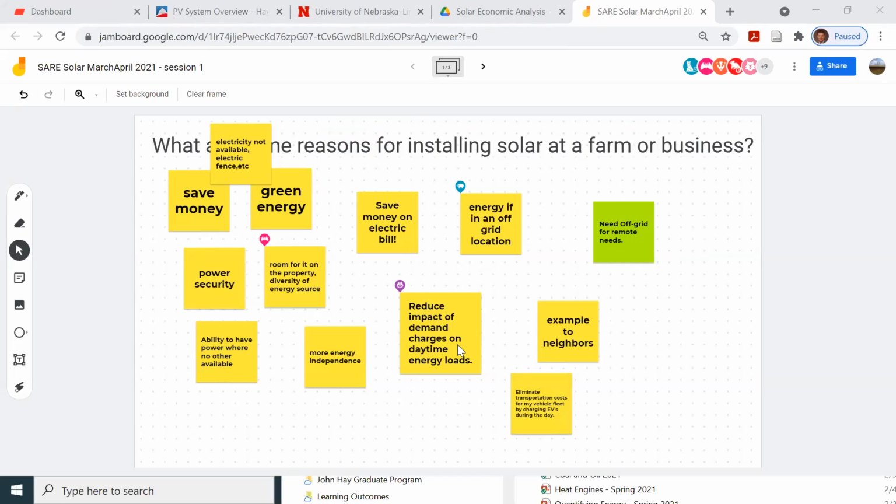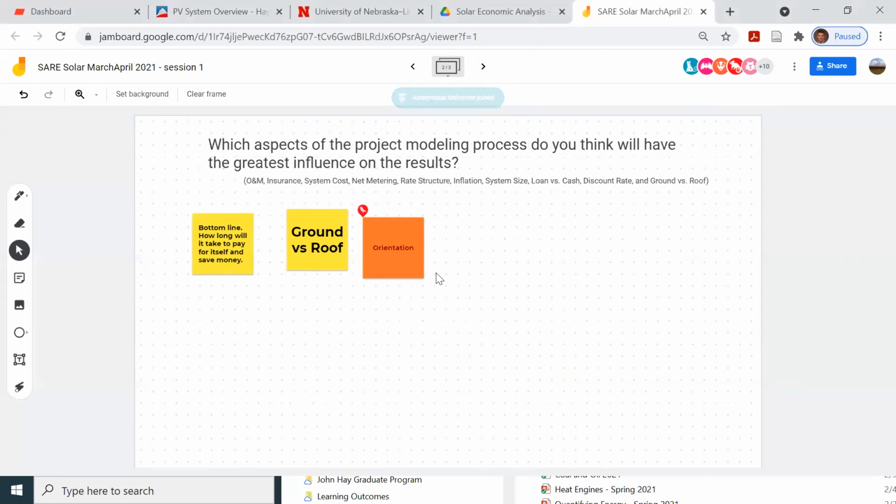So if you have hourly usage data, you could import that hourly 60-minute energy usage data, then the model would be able to look at it and see, based on when they're using energy and based on the weather data that shows when we're going to be generating, are we offsetting demand? The model can do that, but the way that I just estimated it, it won't with that example, because you need that additional information.